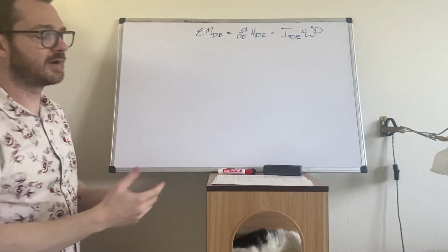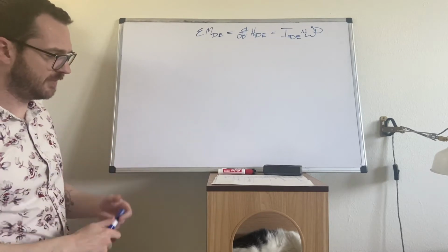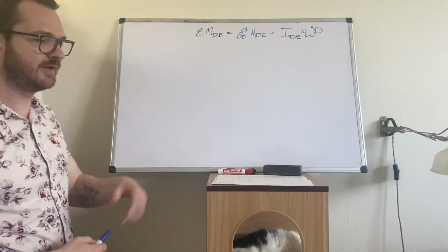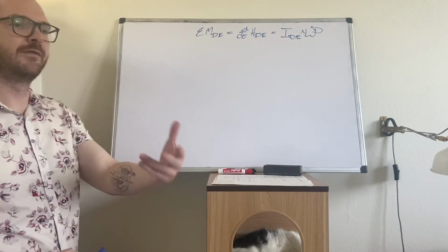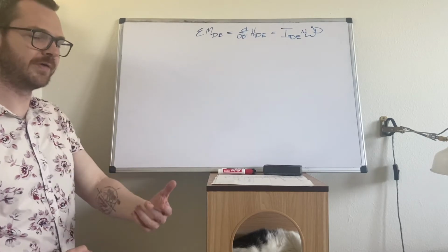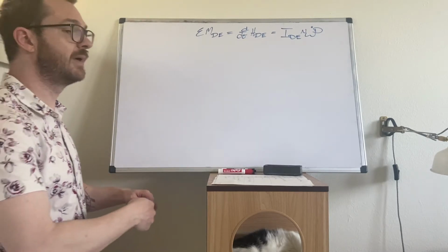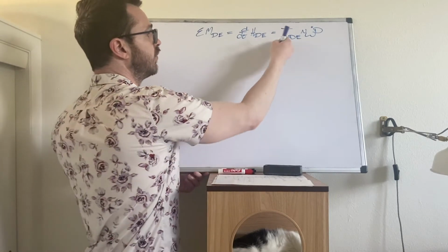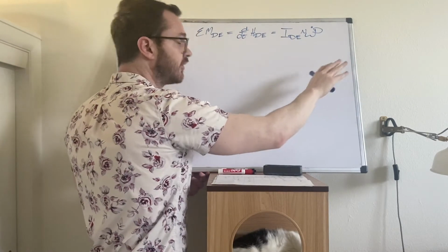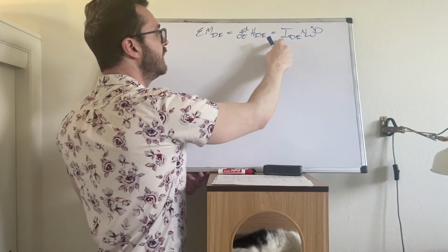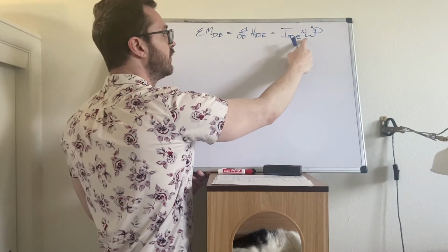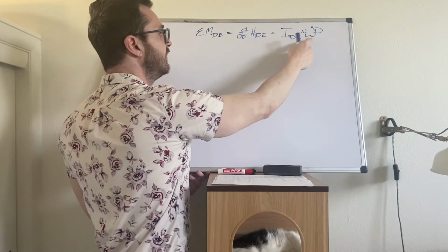We're also modeling the pendulum as a symmetric body, and it's doing a simple rotation. So again, feel free to go through that algebra. You'll find that the cross product term, omega cross I omega, is also 0. So what we're going to be left with after all those terms are eliminated is the modified inertia multiplied by omega into d dot.